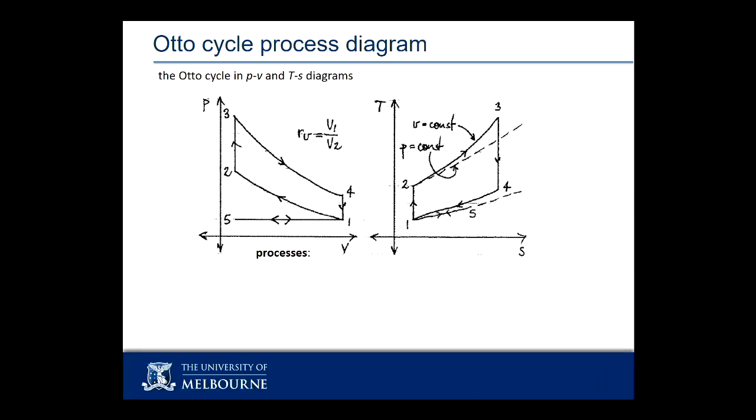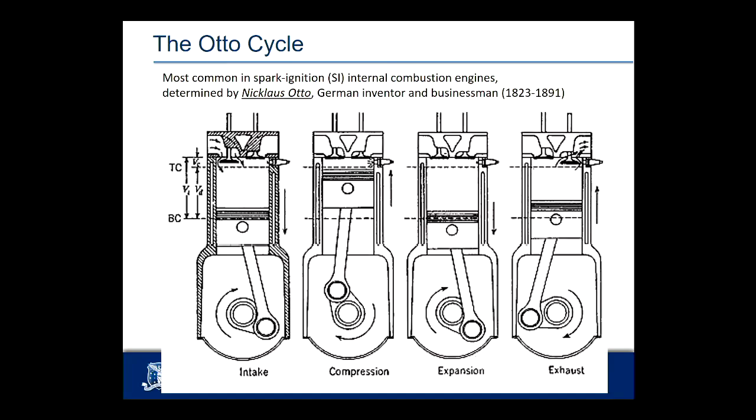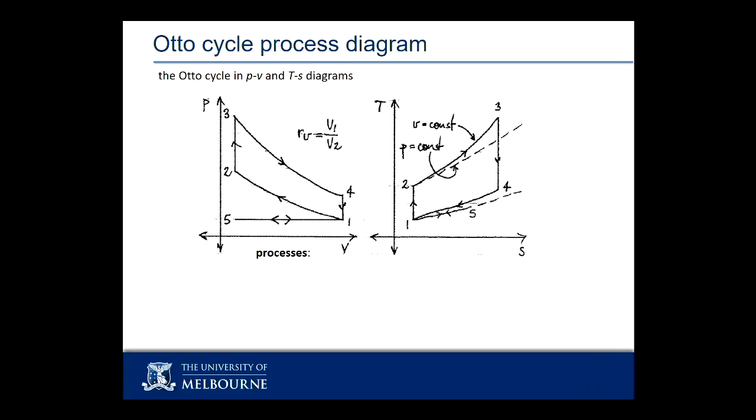We treat the power part of this cycle. The compression and expansion are the bit that we mostly concern ourselves with, because they're the bit where I really have to push and I really get my work out. During those two processes, my valves are closed, which is to say this is now effectively a closed system. No mass crossing the boundary. I'm going to ignore the fuel mass for now, because I'm treating that as a heat addition, as a Q dot, rather than a mass addition.